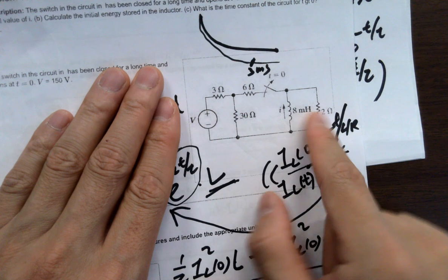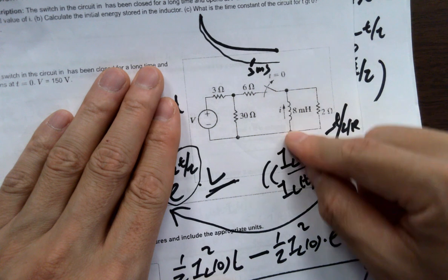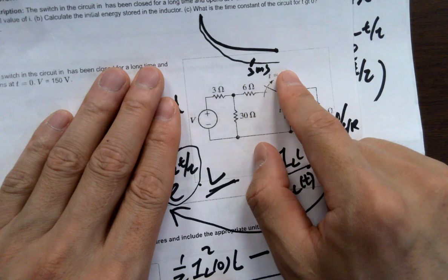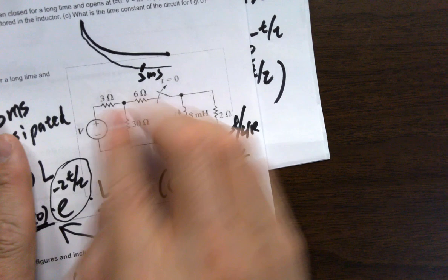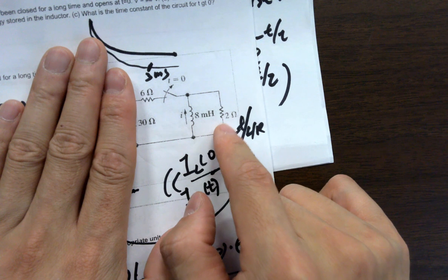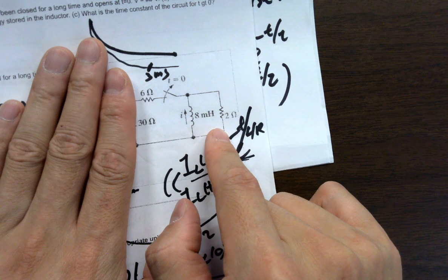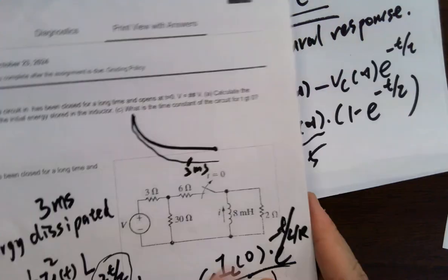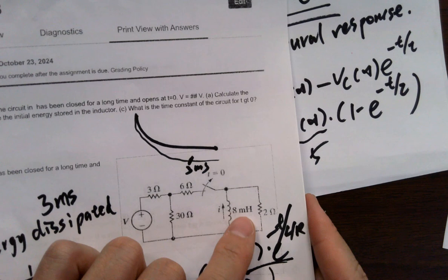It's shorting this circuit, but you still have a current, which becomes the initial current across this inductor. If you open the switch, okay, so this is gone. So this is going to discharge across this resistor. Okay, that's a natural response. I believe people who have been attending classes should be very familiar with this type of circuit. Make sure you can do this.